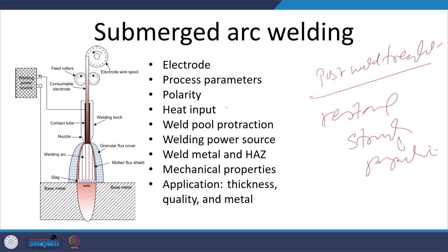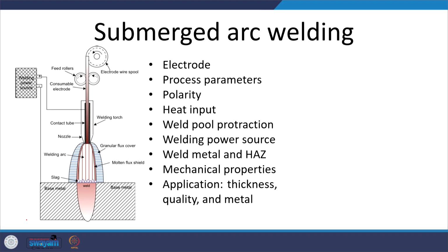And all these are coupled with the high heat input. Higher heat input means a larger weld cross section, wider heat affected zone, and greater degradation in the base metal properties, especially in the heat affected zone, and therefore, it will require the post weld heat treatment for restoring the structure and properties.